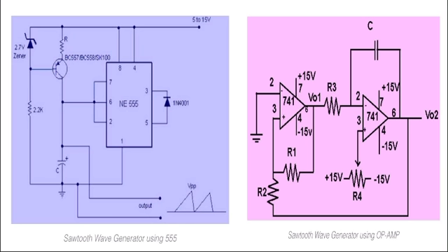It consists of a transistor, a capacitor, a Zener diode, and resistors that form a constant current source, which is used to charge the capacitor. Initially, just assume that the capacitor is fully discharged. So the voltage across the capacitor will be 0 and the 555 output is high because of the internal comparators connected to pin number 2. Here the capacitor starts charging toward the supply voltage, because the internal transistor of the 555 that was shorting the capacitor to ground opens.